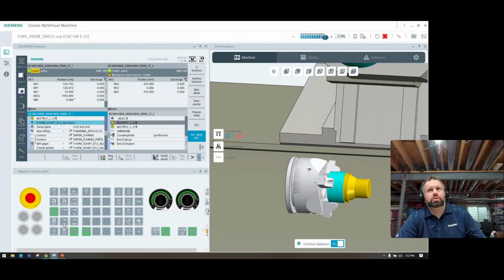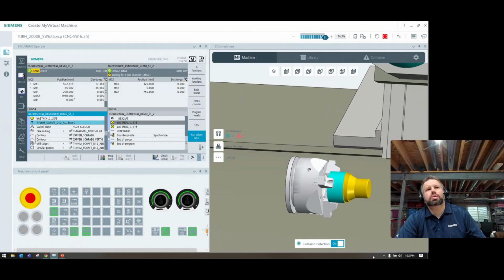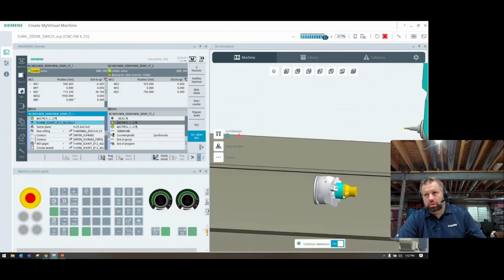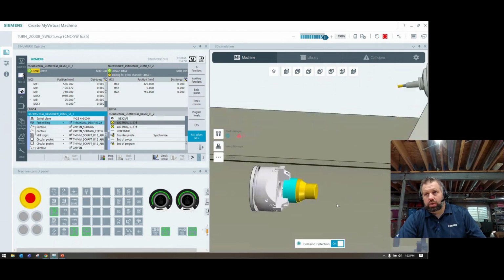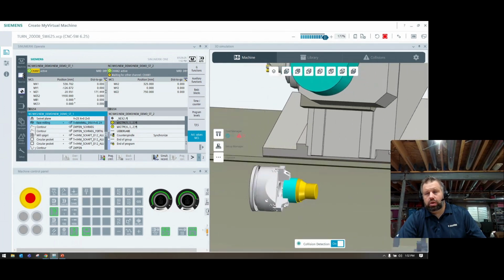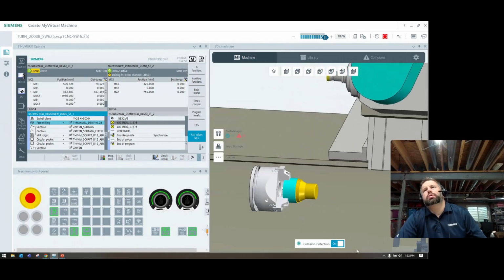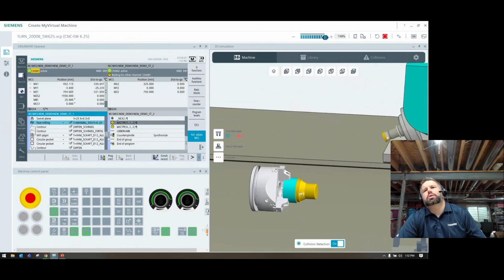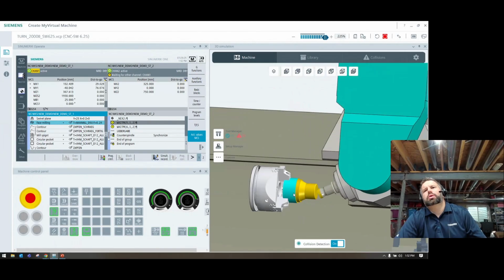That would be a challenge. So a boring head is going to allow you to handle simpler geometry, but once we get to something a little more complex, even tapers like cone shapes, we can do any contour in interpolation turning. I think that and the ability to support any diameter size with that same tool comes into play.